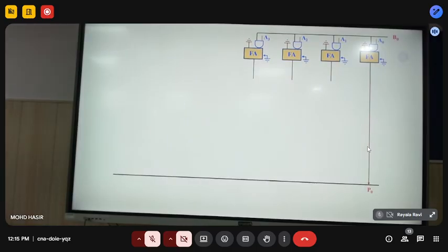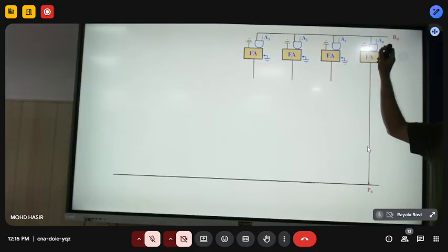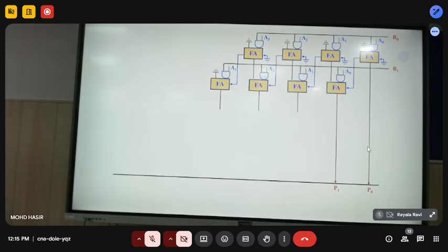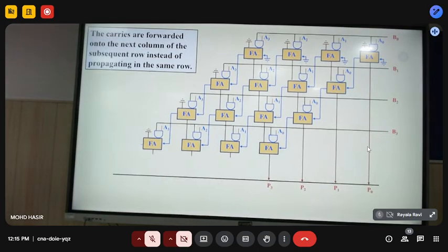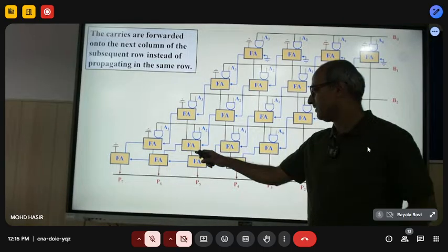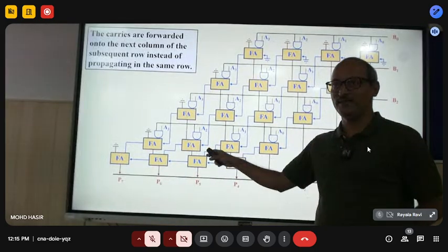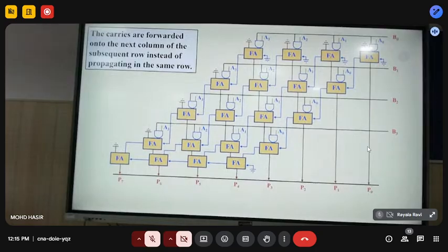So now, replacing every half adder with a full adder. And wherever there is a half adder, I don't need the other two bits. Whichever bit is not required, just for the production of this bit, we don't need this. So both inputs are 0. Okay. So everywhere half adder will get replaced with full adder. Some resources are restricted. Okay. Now this is the half adder, full adder, and then another, because here there will be carry generation. We need to accommodate it. Okay.